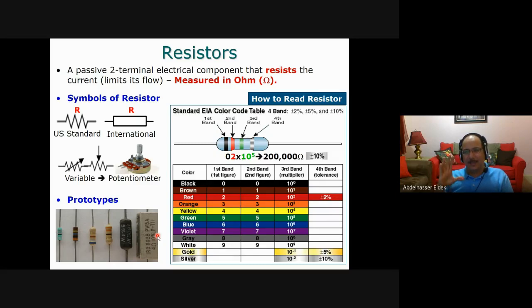It is 4 ohm but has a 10% tolerance, which means plus or minus 10% of its value. There is an error in this one. This one here is 180 ohm with 5% tolerance. And here it says 4 watts. This is the maximum power, otherwise it will burn.